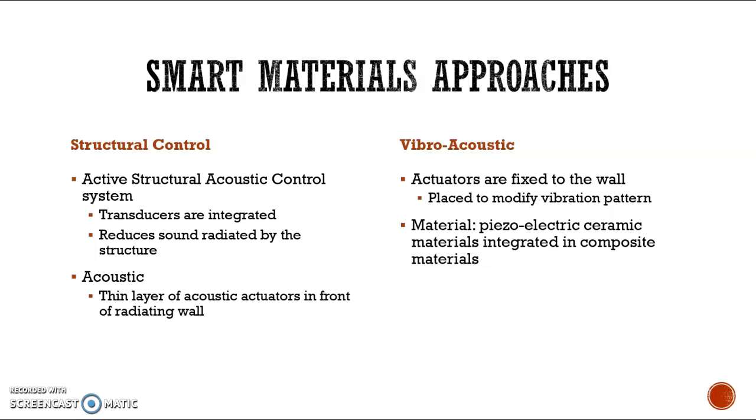The other approach is vibroacoustic approach. This approach is when actuators are fixed to the material of the wall. The actuators are placed to modify the vibration pattern so that the wall does not radiate the sound. Commonly used materials for transducers are based on piezoelectric ceramic materials integrated in composite materials. The authors also suggest an active